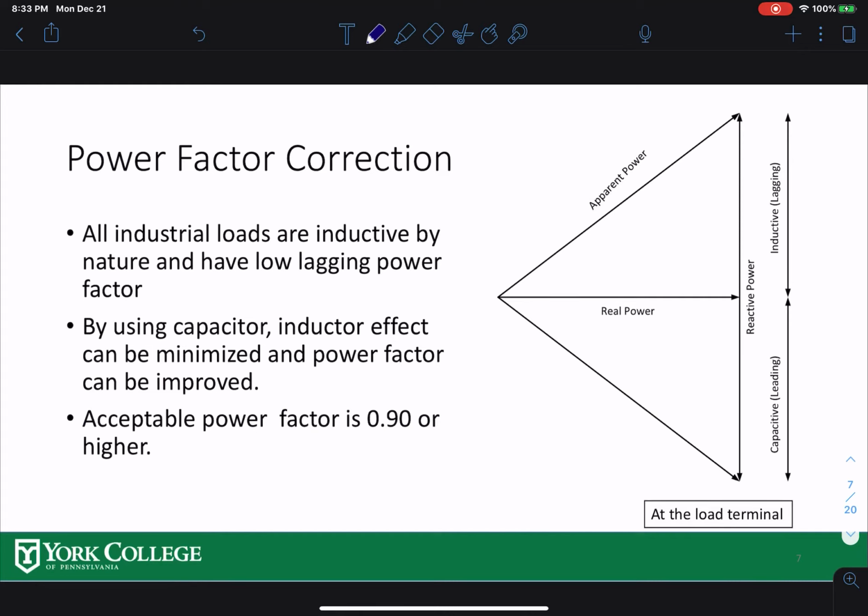So how do you do power factor correction? Normally, is it always true that most loads are inductive? Look at the loads in industries: all motors. Motors are big inductors, right? And at your home, you have HVAC systems, fans, AC, the pump in the refrigerator, all are inductors. So loads are normally inductive.